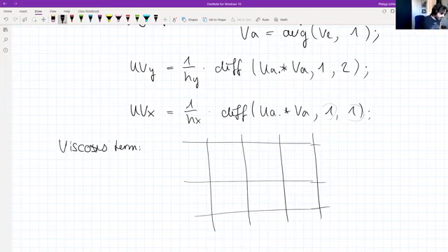So if I want to calculate, for instance, for the streamwise momentum equation, the points where the streamwise momentum equation is defined, and I want to calculate the derivatives in a point. If I do it in x, this would be index I. This is I plus 1/2.